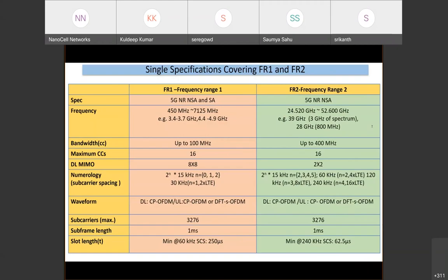So there's a question about, can we use FR1 for control and FR2 for user plane? Absolutely possible. This is a question from Anupam. Definitely, yes, this is one of the possibilities. When we say control, we should be clear about it. I'm assuming at some level you can keep a link which, at an application level, can be a control, and it can be having the high data throughputs through FR2. That's possible. Okay, so you can't send PDCCH for FR2 and FR1. If that is what you mean, then that's not there.